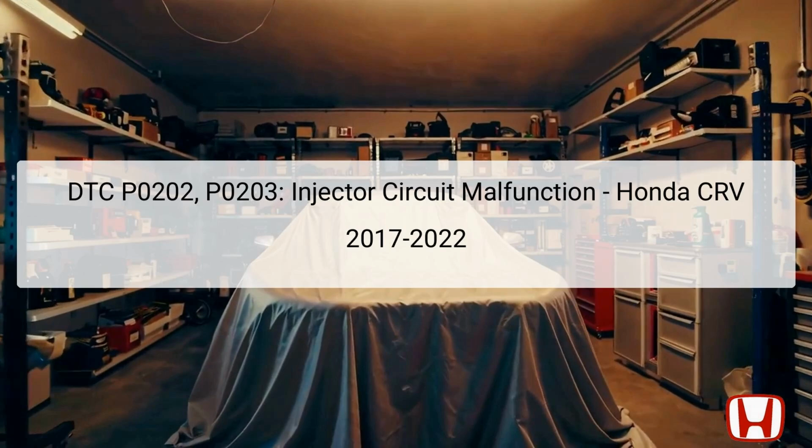Welcome to our diagnostic troubleshooting presentation focused on DTC codes P0202 and P0203, representing circuit malfunctions in the number 2 and number 3 cylinder injectors in the Honda CRV models from 2017 to 2022. These diagnostic trouble codes, DTCs, indicate potential issues with the fuel injection system, specifically related to how the engine computer communicates with the fuel injectors.